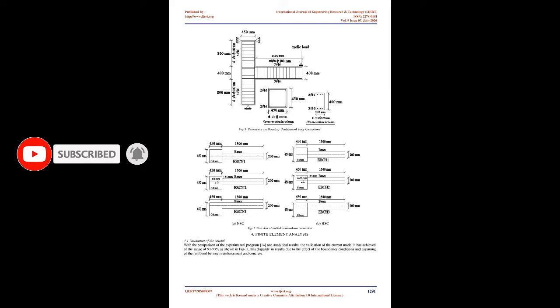Previous studies indicated that beam eccentricity leads to unsymmetric damage in the joint due to additional shear stresses caused by torsion. This damage resulted in pinched load versus drift hysteresis curves for the subassemblies and low energy dissipation capacities. Consequently, in the recommendations of the ACI Committee 352, the shear strength of the eccentric beam column connections is decreased by using a smaller effective joint width if the eccentricity of the beam to column centroid exceeds 1/8 of the column width.